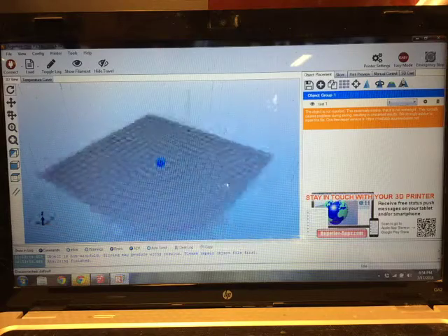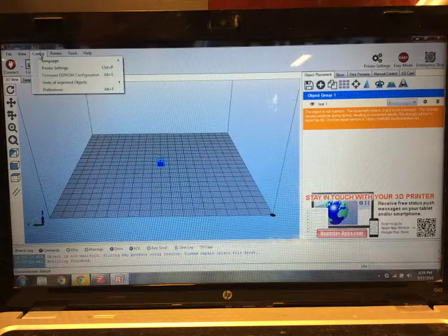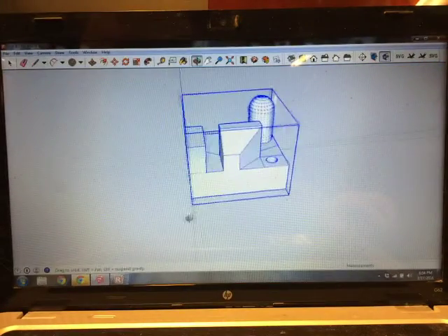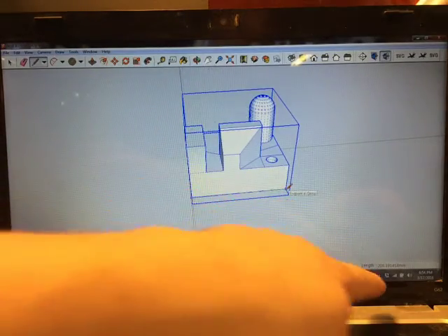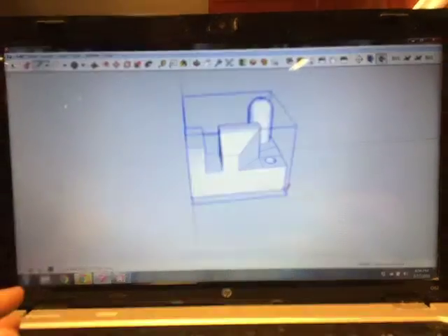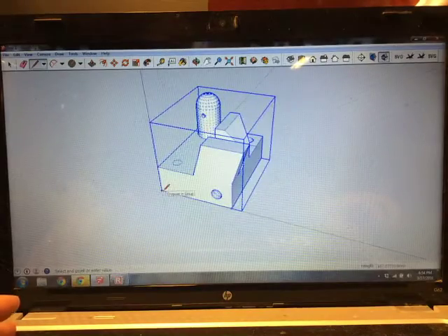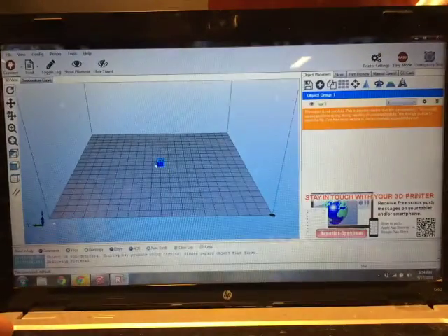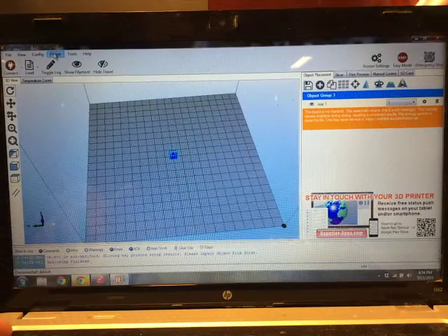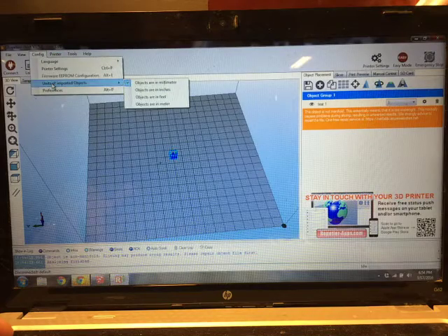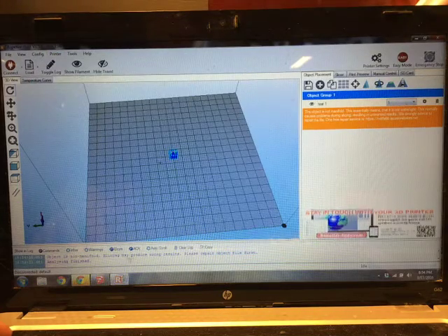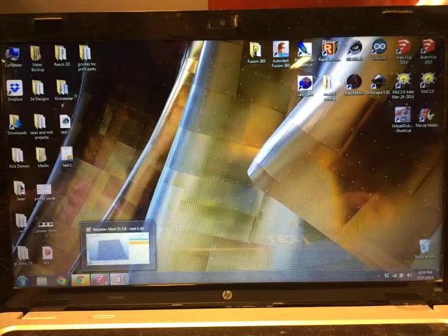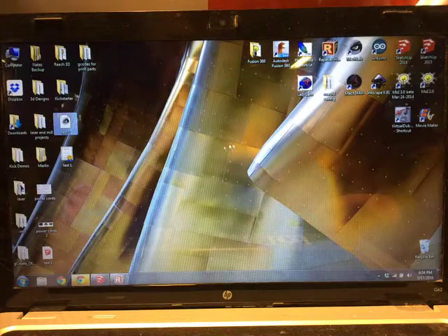I think that thing is way smaller than what we drew it. Let me actually measure it, just real quick. Let's see what's going on here. Okay, from end to end, 208. This thing should be the size of our printer bed, a little bit longer than the printer by 167. So what happens is this thing is imported in inches, or no, it's imported in millimeters. The thing about Meshlab is that you can scale it if you want and change the, so let's see.